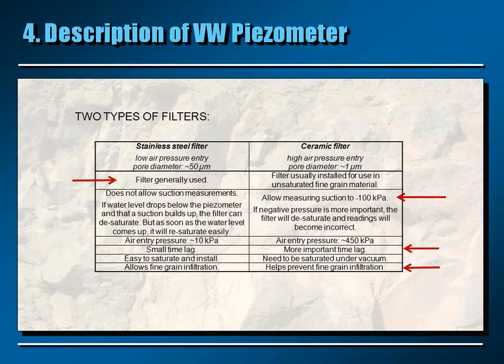So the standard type is the stainless steel filter. But if someone is installing a piezometer in clay, they might consider using a ceramic filter.